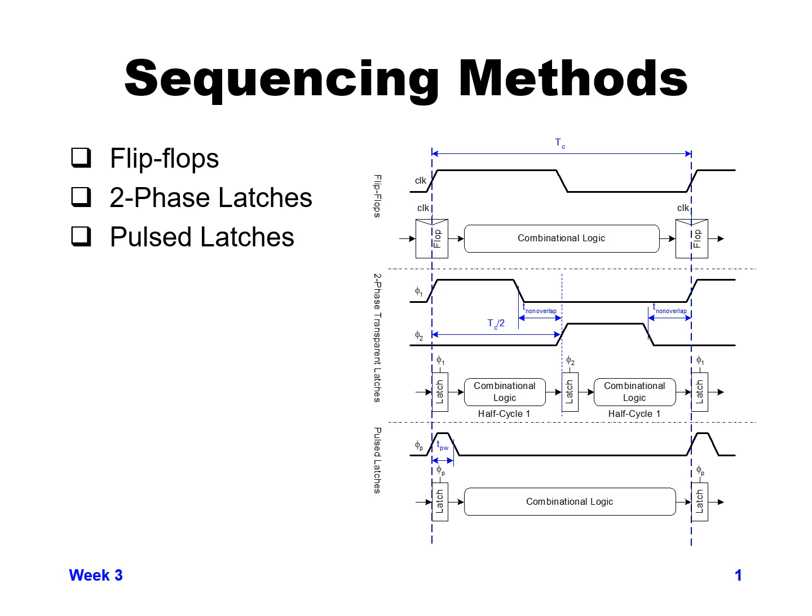Finally, the last one at the bottom there is showing how you can use latches to perform the same functional performance or same functional logic as what a flop does. So if you, instead of using a normal two-phase clock to go into a latch, send a clock that's a short pulse clock into a latch, it functionally behaves kind of like a master-slave flop does.